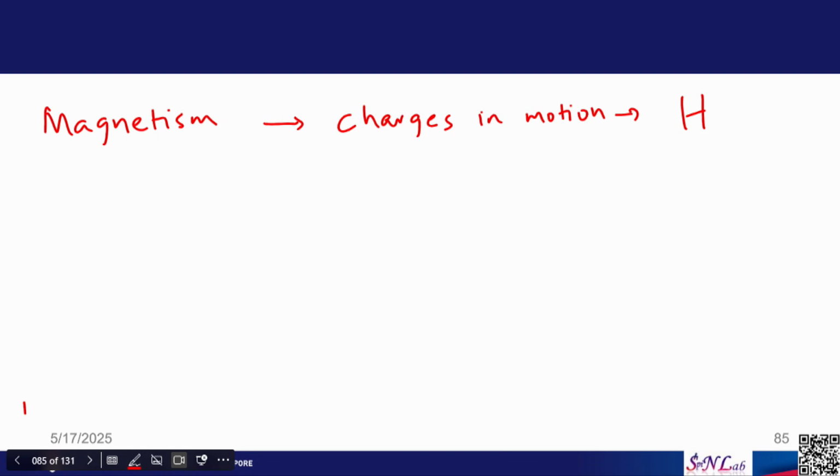So you can produce different amounts of magnetic field depending on the strength of the current, the windings of the coil, and whether you have a ferromagnetic core with a permeability mu r. So we learned that this mu r can enhance the magnetic field produced by a certain current in a coil. Okay. So this is the first concept that we learned.